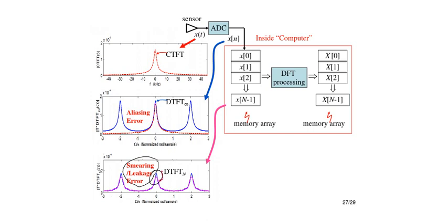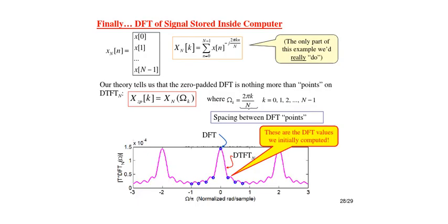Now in real time we can compute DFT, right? So the DFT expression we know already. This is the DFT expression. So essentially what DFT does is just draw the points from the truncated DTFT. So it is just drawing the points. So when you append zeros, it will draw more points in between, so that grid error can be reduced, but smearing will still remain as it is.